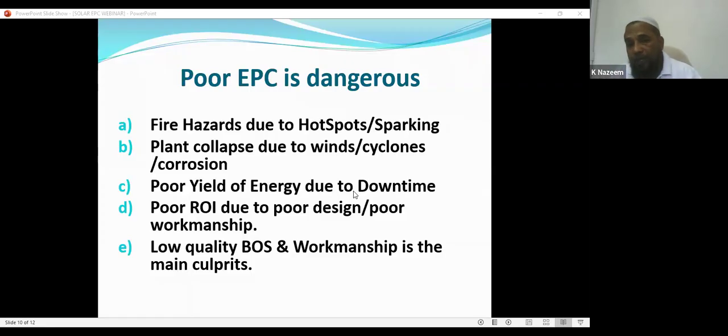Now, because of the cable, we are losing 1 volt. So when it shows 10.5 volts, actually it is 11.5 volts, because of the cable. So this difference from 13.5 volts to 10.5 volts, the 3 volts, is for 4 hours. Now at 11.5 it is giving cutoff, so the backup time is reduced. So by just keeping the batteries closer to the UPS, the problem was solved.